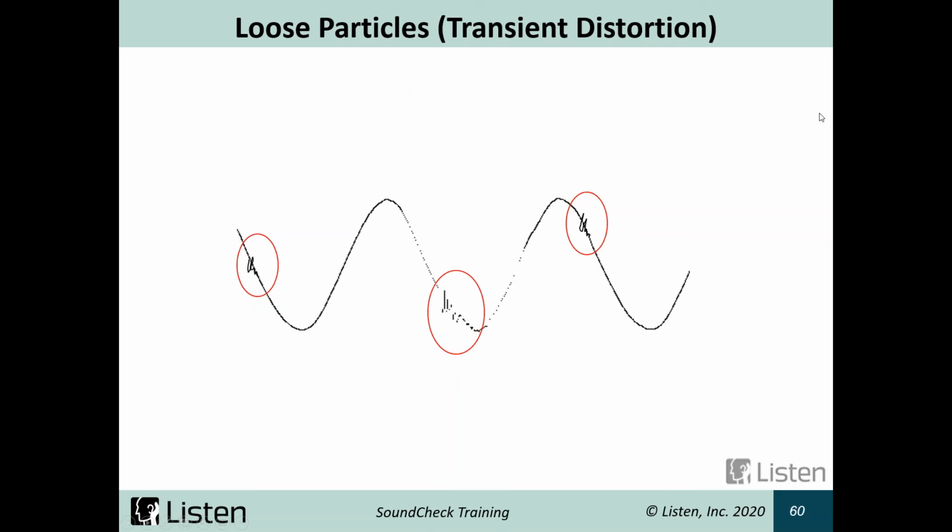So here is a waveform, and this is what we're catching. We're catching randomly spaced occurrences of transients. The spectrum is random noise. There doesn't have to be a distinctive pattern. And these are usually randomly spaced, and they're so far apart they can be heard as distinct events. So it can be similar to rub and buzz. It can catch some things in there as well, but a lot of times, instead of sounding continuous, it'll sound more randomized and as distinct events.